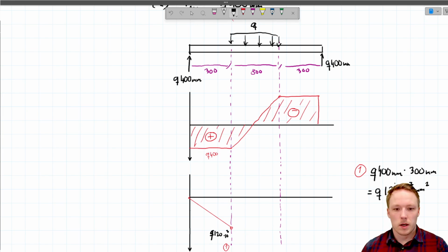Okay, so that's our internal bending moment there. All right. Well, then you remember that the distributed loading causes a parabolic distribution in bending moment, and when we go from point 1 to halfway of this distributed loading, that is the point where we are going to have a local minimum or local maximum of bending moment.